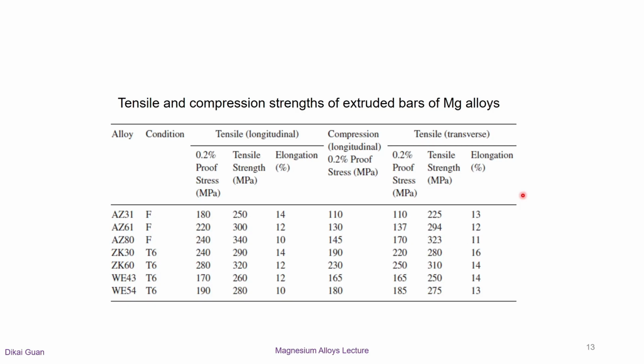The commercial magnesium alloys WE43 and WE54 do not suffer from the yield strength anisotropy problem. Their tensile properties are quite uniform when tested along the directions parallel and perpendicular to the extrusion directions. Again, suitable composition is key to adjust the mechanical properties in magnesium alloys.